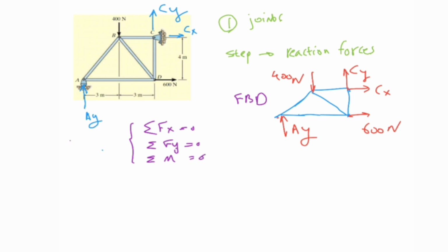Meaning that I have Ax, Ay, Cy and Cx as the unknowns, I have three unknowns and three equations, and I can solve this and find the reaction forces. This is the first step that we need to do.